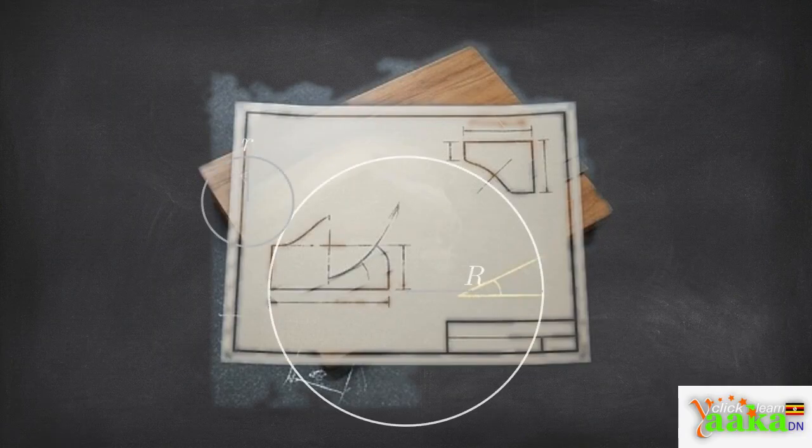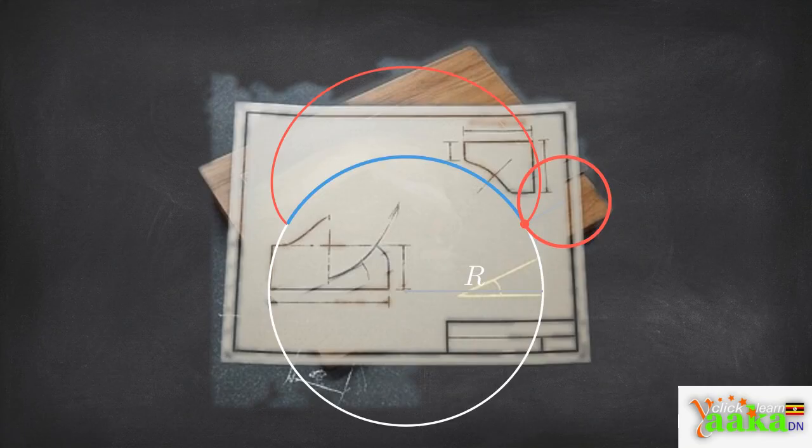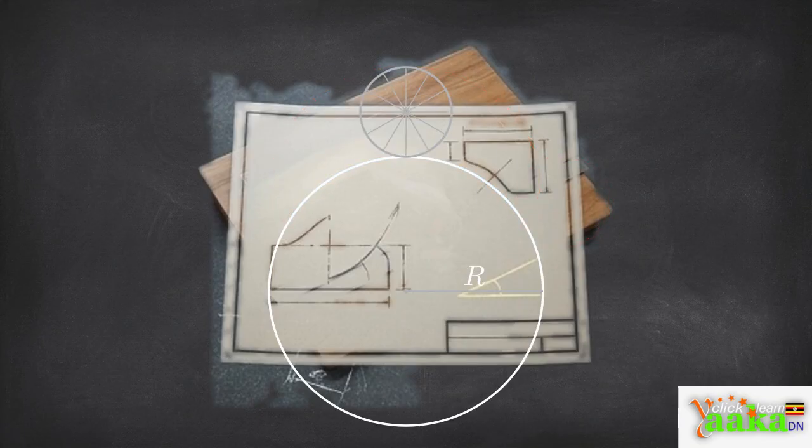This animation shows an epicycloid, the exact path traced by a point on the circumference of a generating circle rolling along a stationary base circle. To roll without slipping, the highlighted blue arc segment must exactly match the generating circle's red circumference. Because you will divide your generating circle into 12 equal parts, you need to find the exact angle for each matching step on the base circle.